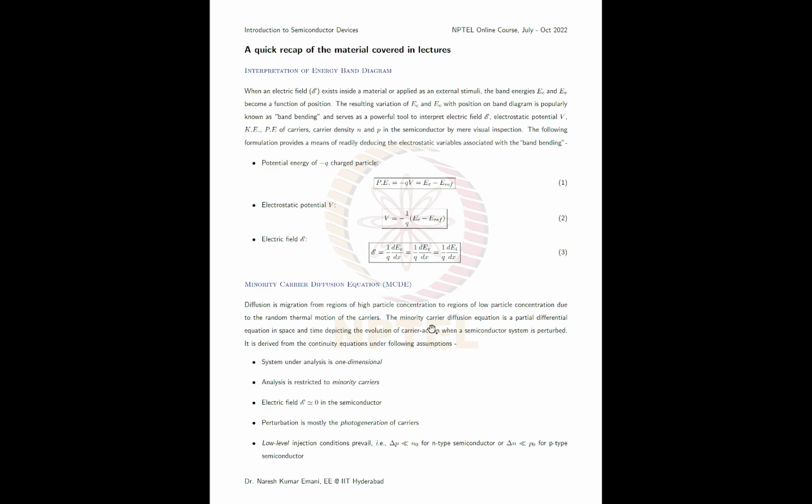The minority carrier diffusion equation is a partial differential equation in space and time depicting the evolution of carrier concentration when a semiconductor system is perturbed. At equilibrium, a semiconductor has a constant particle concentration throughout, but if you perturb it so that some regions have higher particle concentration and others lower, then the particles will try to equalize themselves.